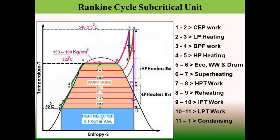But the purpose of circulation is very clear. It actually intends to continuously wet the surface of the water wall tubes and necessitate the heat absorption at a rate which is not detrimental to the tube surfaces.